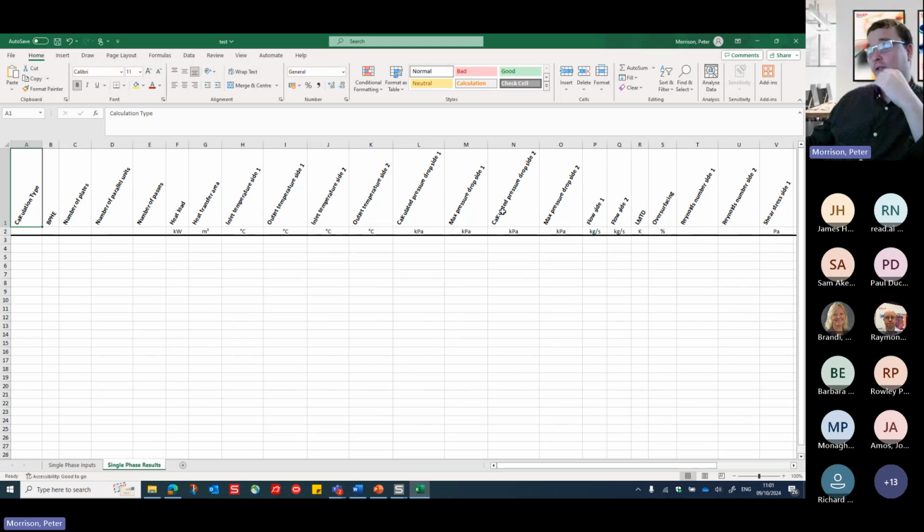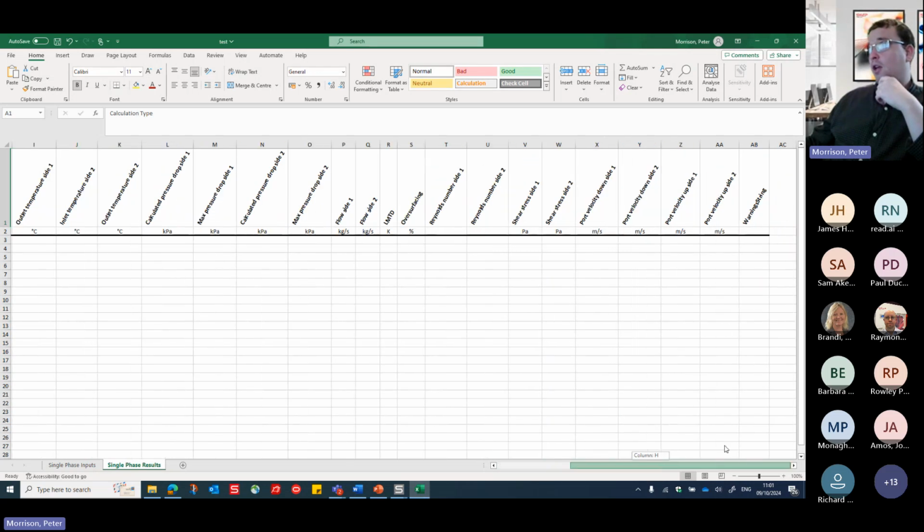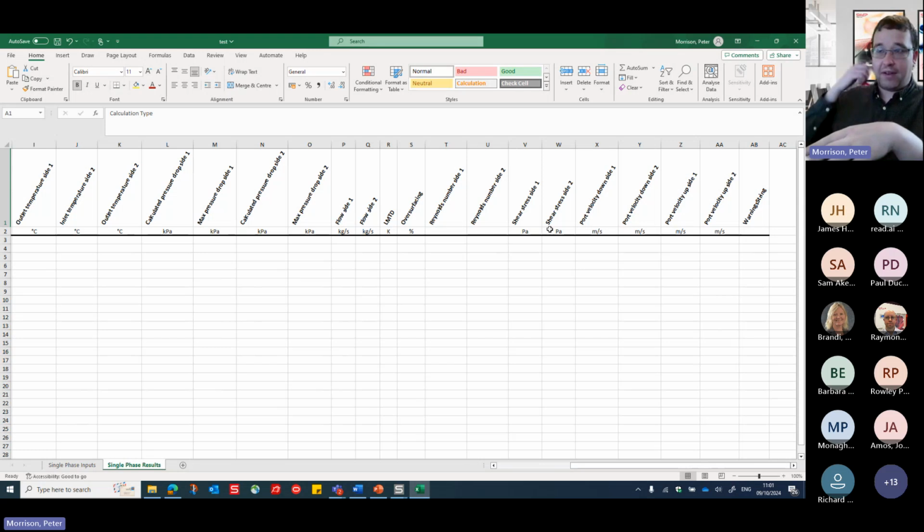So you can then sort of say, right, is the pressure drop okay? Is it adequately over surfaced? Is it good Reynolds numbers, good shear stress? Reynolds number is about is it turbulent enough, which is something again we cover in the CPD. Shear stress is it high enough to make sure that we don't have any calcium attaching to the unit that could block it. So once you've done that, you have all the information you need in this Excel sheet.